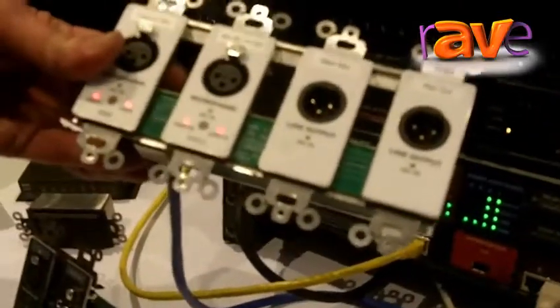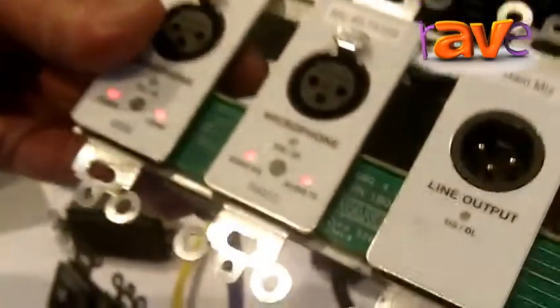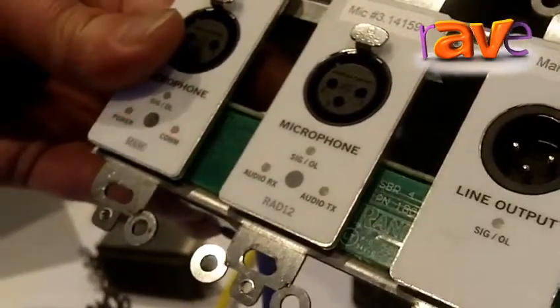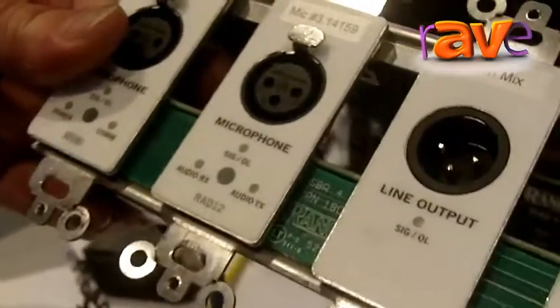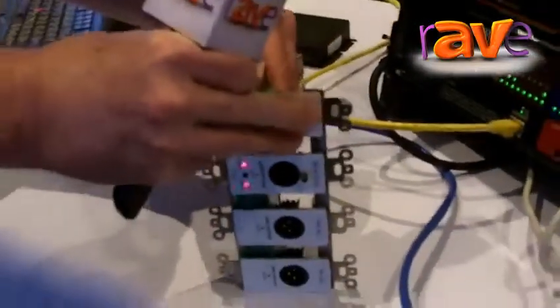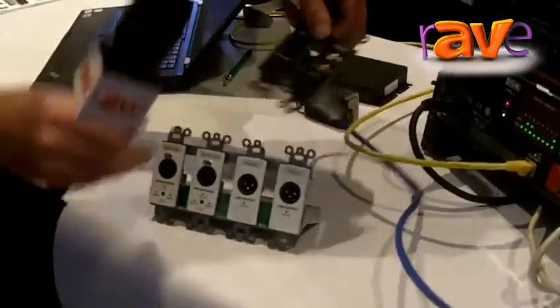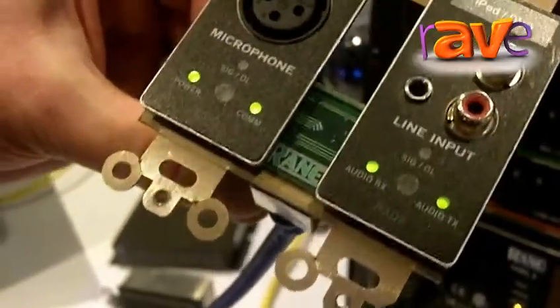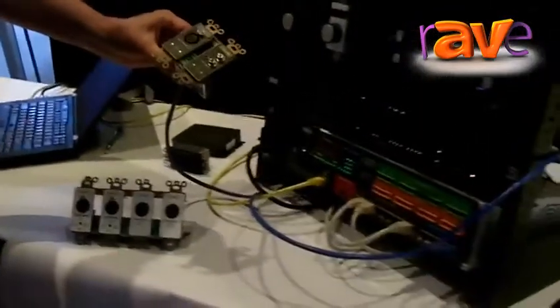So what you do is you pick a RAD device like this. This particular one has 2 inputs and 2 outputs on it. The flashing red lights are a good and bad thing. The flashing red lights mean that it's testing the cable and the cable is good, but this is not the device that it expected to see on the end of it. If I then plug in the correct device, in this case a RAD 2, now it shows green and it says that's what was expected to be on the end of this cable. So not only does this confirm your design, but it keeps a constant watch on the hardware as well.